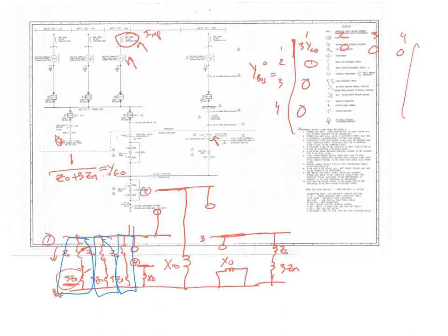The transformer essentially, so here's your neutral that goes, this is actually to ground. This actually literally runs through a transformer with, I think in this case, a resistor through it. So that resistor actually looks like a really large resistor that goes to the generator phases. So this is the actual high impedance ground. You've got a big resistor represented in there because of the reflection of the turns ratio, right? This is a 7200 to 240 volt transformer, which means whatever this resistor is, Rn, it's going to be Rn times A squared on this side of the transformer, right? On the primary side of the transformer.